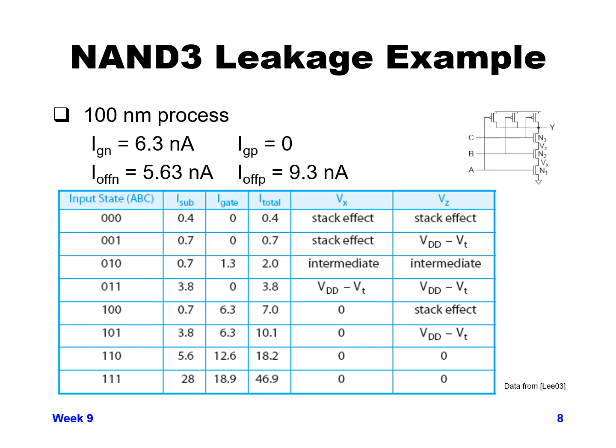The main thing to note is, of course, if more of your inputs are 1, and depending on the combination, you can see a dramatic difference in the amount of leakage. So if all 3 of your inputs are 0, your total leakage will be 0.4. I think that's in the nanoampere range. It doesn't say for certain in the slide here.